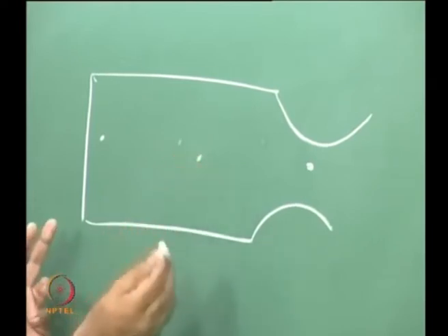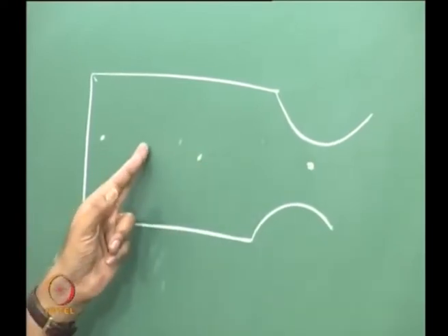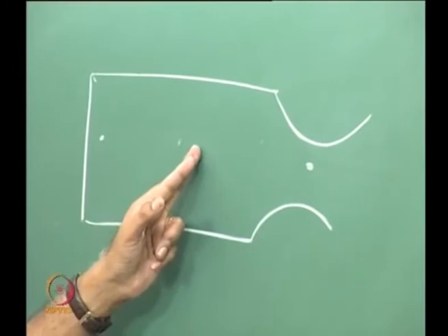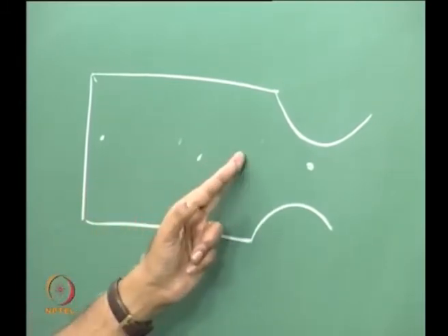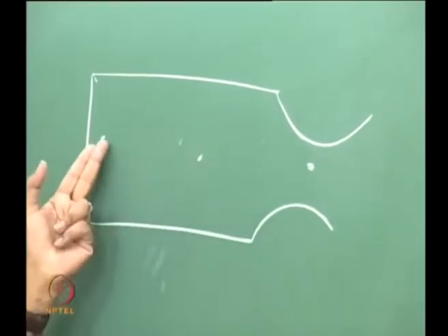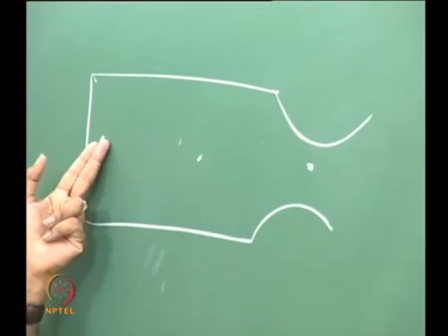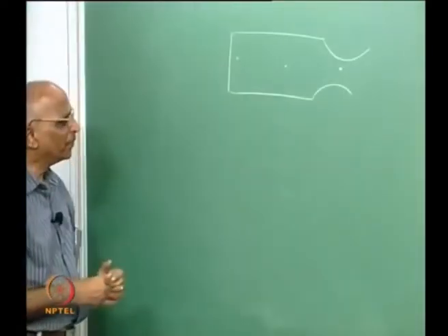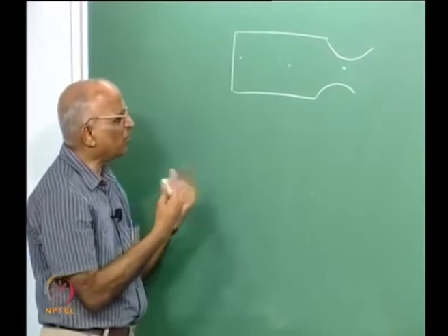a pressure node. If I have higher harmonics, I have a set of a pressure antinode coming here, a pressure node here, pressure node here. So also wherever we have pressure antinode, you could have velocity nodes and vice versa. Now what is the influence of all this?